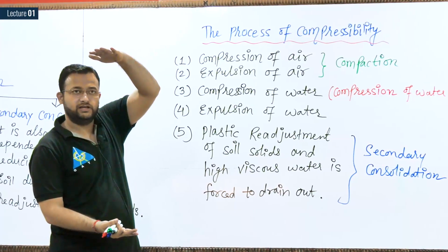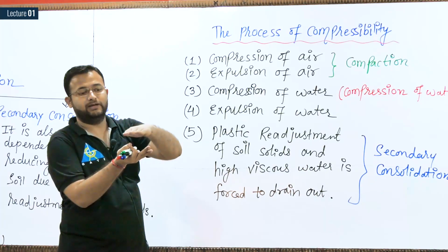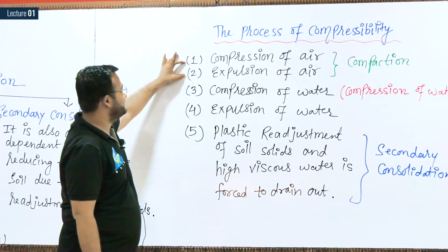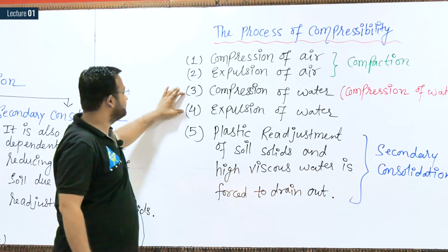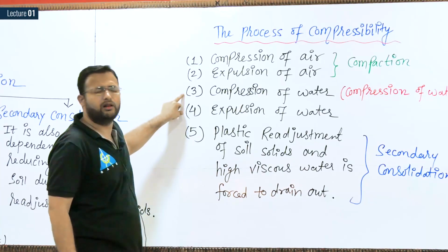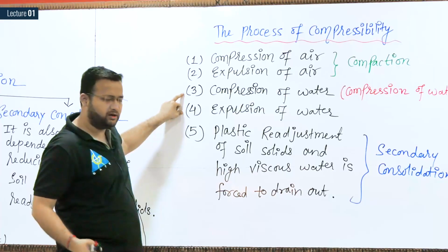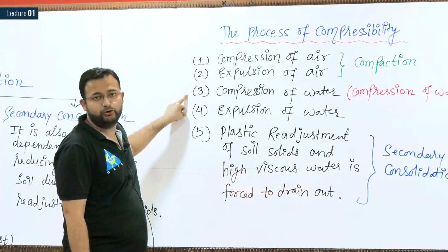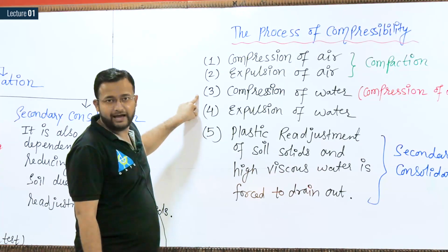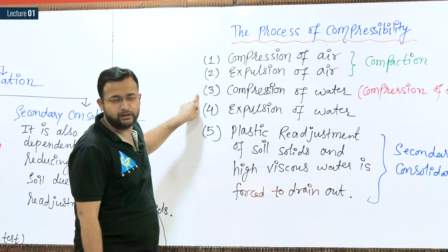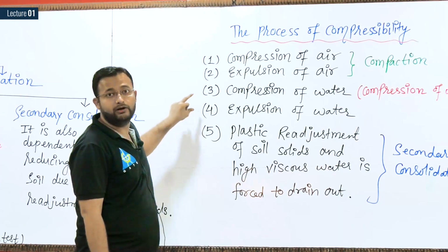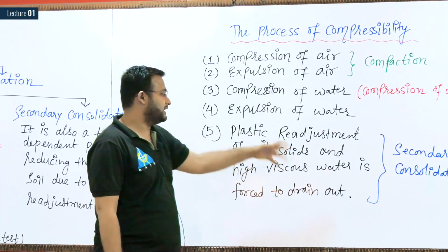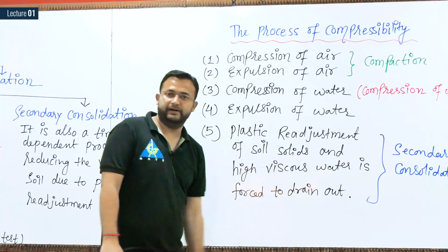Here you should understand, in these stages your compressibility will occur. Your soil volume was initially like this, after secondary consolidation it will be like this, very less. Now first thing people should understand, these two stages occur immediately. Stages 3 and 4 will take a lot of time. Primary consolidation is time dependent. Since it takes a lot of time, this time is called hydrodynamic lag. We will be discussing this in the coming lectures. Infinite time it can take. Then after this, secondary consolidation may occur. It is also a time dependent process.